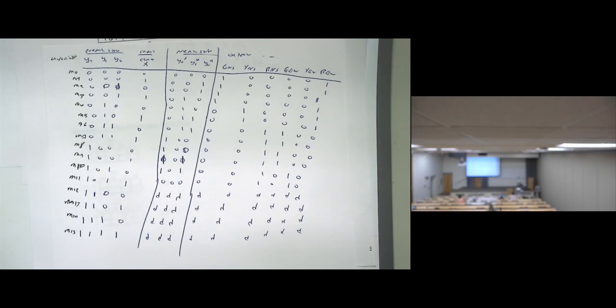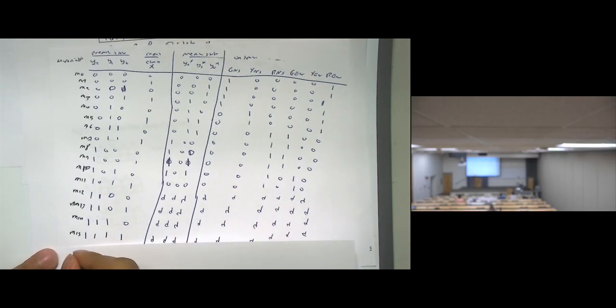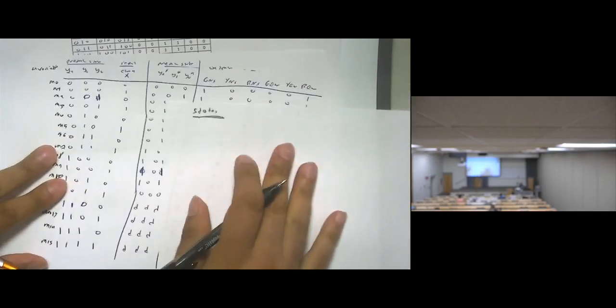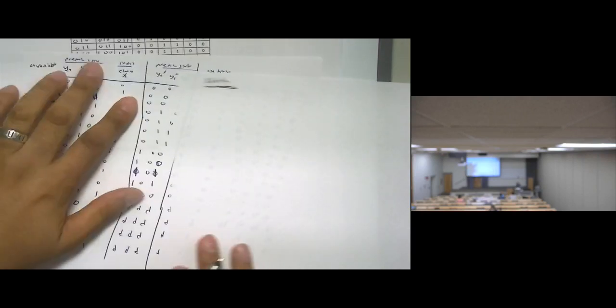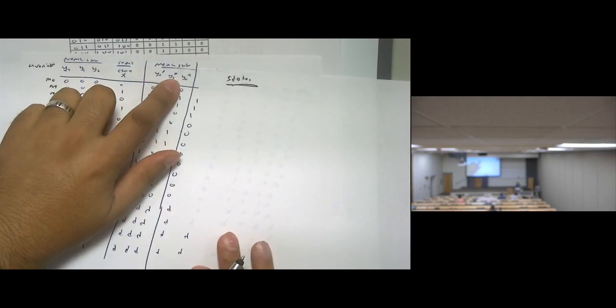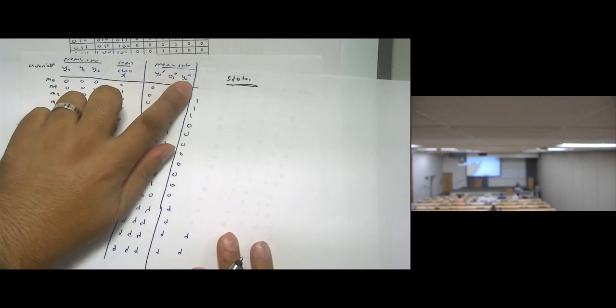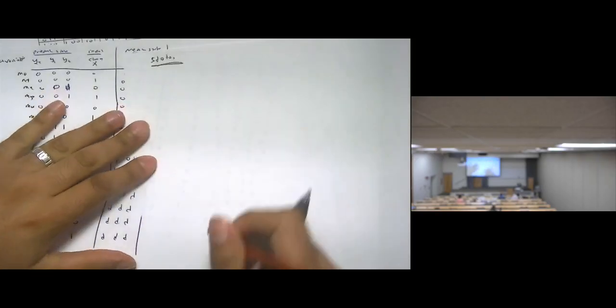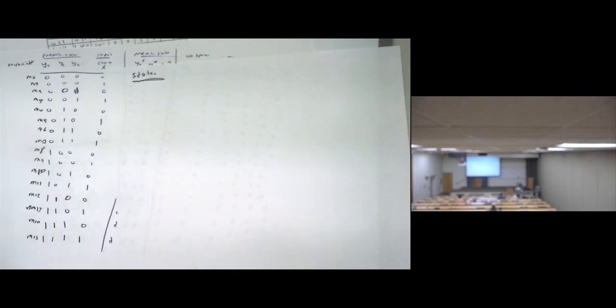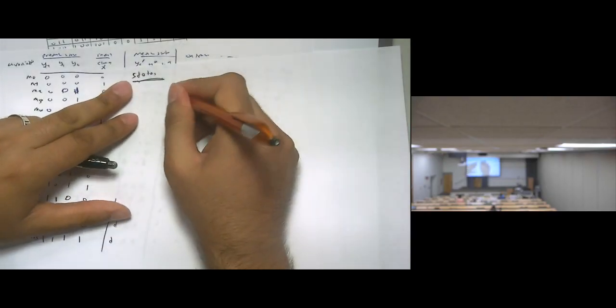Okay. Now, here are the Karnaugh maps. We can apply Karnaugh maps here. Let's make Karnaugh maps for the states. Let's work for the states, which are y1, y2, y0. We have 3 states, with next states y1 star, y2 star, y0 star. Then we need to make 3 Karnaugh maps, 4-variable Karnaugh maps.